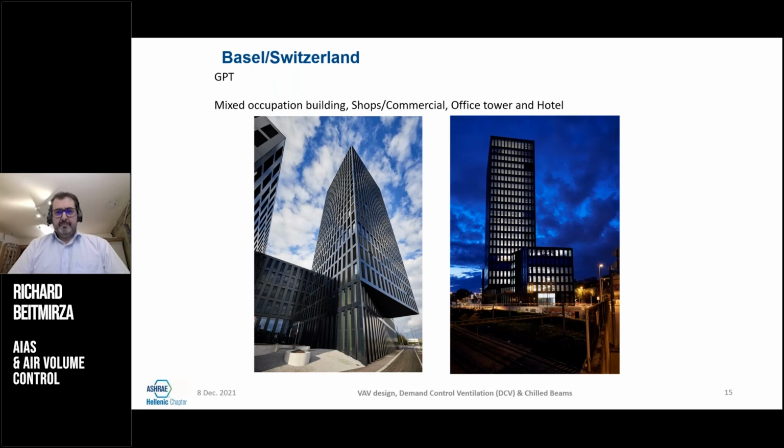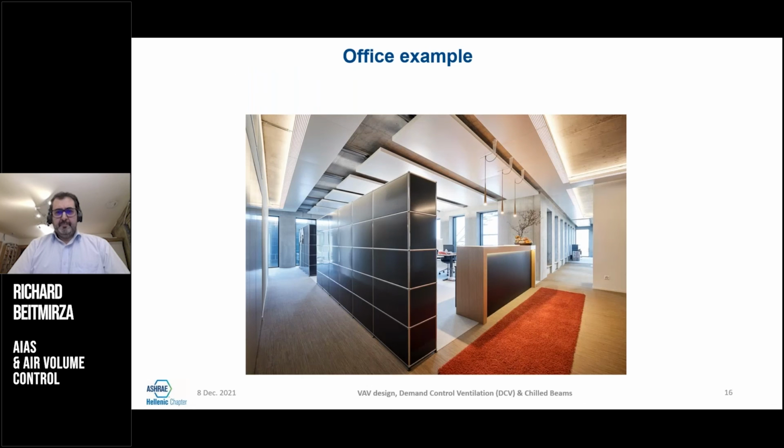And doing this, I think we had about 400 to 500 VAVs on different levels that were installed. It was a very prestigious building. So this can be taken to a very high level. And the complexity was that although this is an open platform, it is at the same time using VAVs per zone, and we are dividing it into 7 sections.